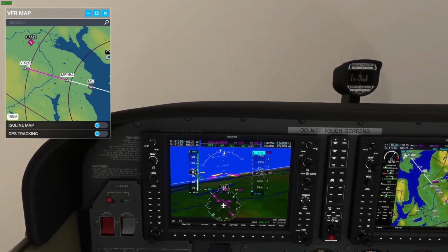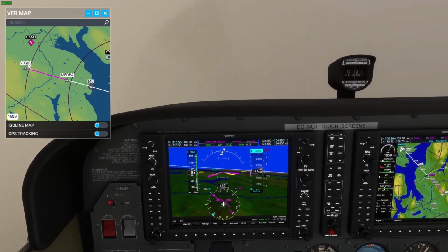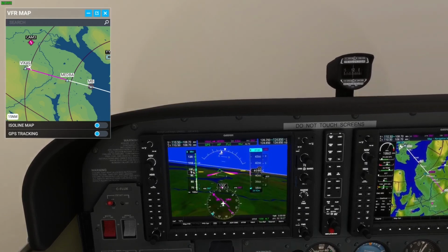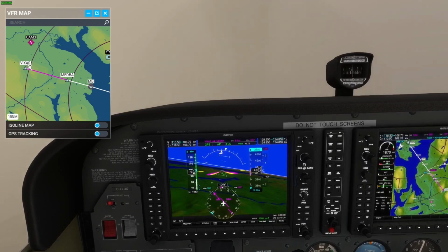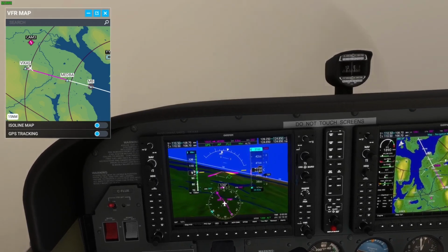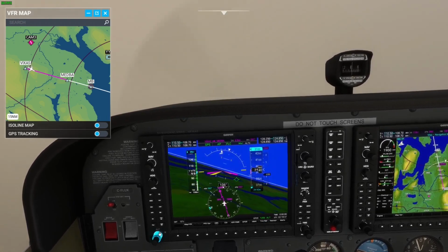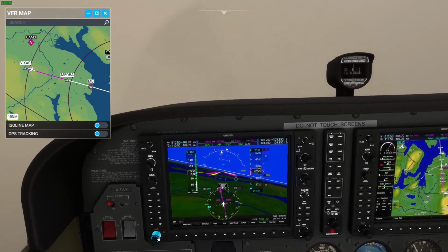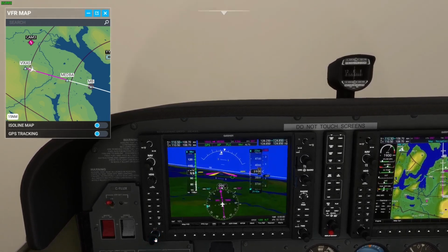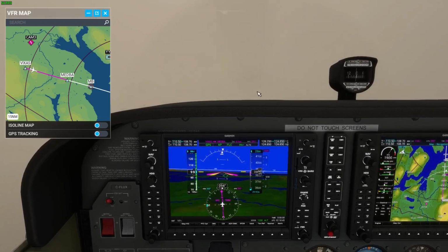Now, once the plane is flying based on GPS mode tracking direction and altitude, the throttle can be used to vary the speed of the aircraft, because the navigational equipment automatically maintains the vertical speed.